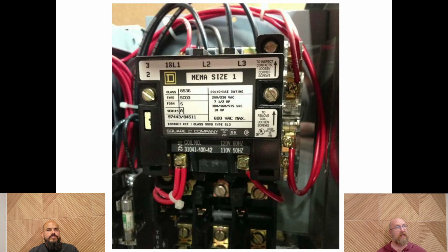On older ones, sometimes those auxiliary contacts are off to the side, like this one right here, where it's just using the mechanical component of that transparent part that's slapped onto the side. That's a normally open and normally closed contact. That's just using the lever that's inside there to have it actuate at the same time as it's closing L1 to T1, L2 to T2.